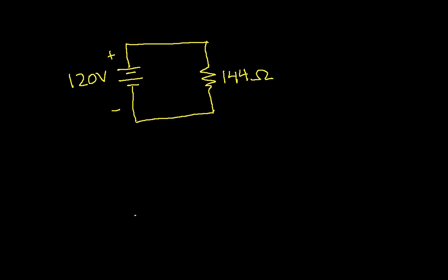This models, in actually a very simplistic way, the connection between a light bulb, in this case we'll discover it's a 100-watt light bulb, and your wall outlet, which if you live in the United States is nominally 120 volts. Now, in the spirit of complete and honest disclosure, I'm lying to you in the sense that the 120 volts you are used to dealing with out of a wall socket is really an RMS value that accounts for the fact that the voltage is an AC voltage.